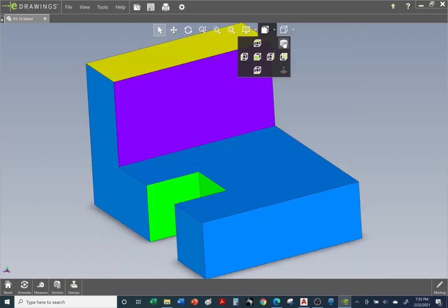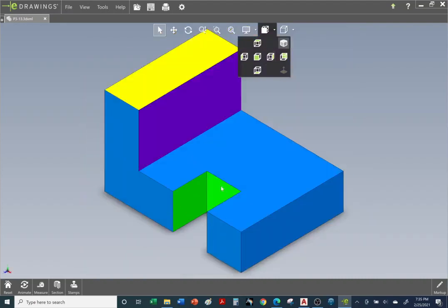If we go back to isometric view, there's this pocket here, right? That we cannot see if we're standing over here on the right. So again, think of Jack's mugshot. Here's the front view for standing here, staring at Jack. And go over to the right side. If you're standing over here on this side of the building, you cannot see this pocket here. So we're going to use a red line to represent the depth of this pocket here.